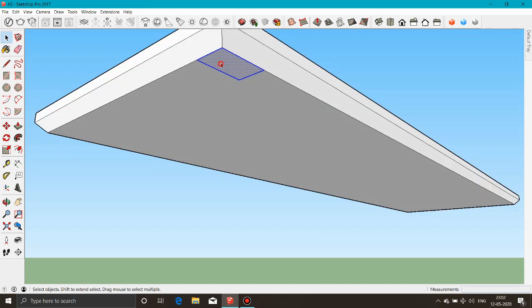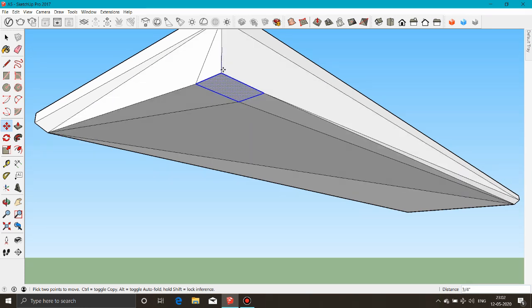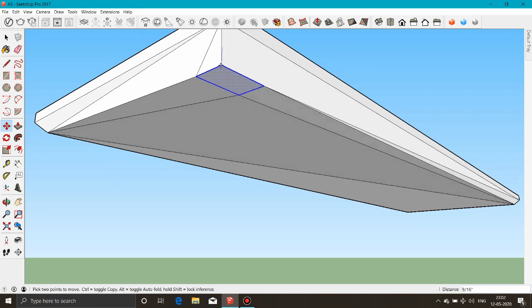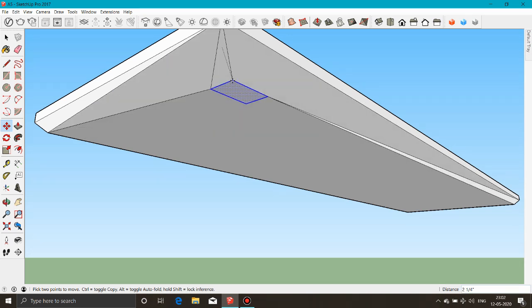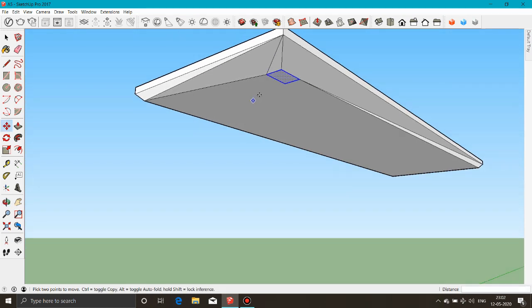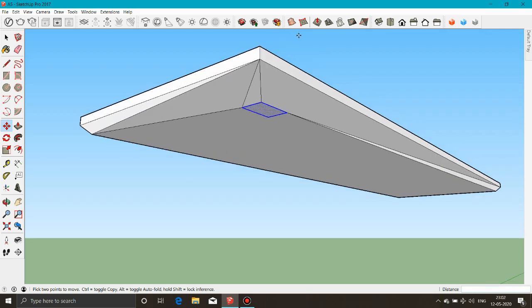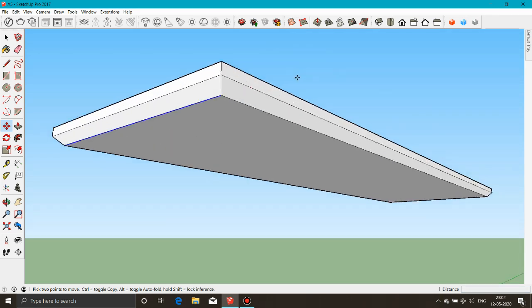This is one of the primary uses of groups, which will isolate our geometry, preventing the edges from merging. To see this in action, undo the rectangle using Ctrl-Z on a PC or Command-Z on a Mac. Then, triple-click to select the whole tabletop, right or context click on the top, and from the submenu, choose Make Group. A new bounding box is shown around the whole top, and it now behaves as a single, unique entity.